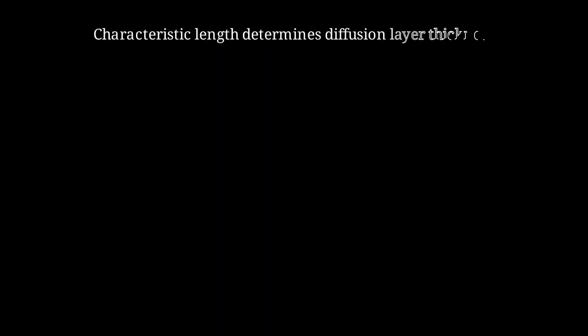The channel width, typically 100 to 1000 micrometers, determines the diffusion layer thickness and residence time. Diffusion layer thickness delta is approximately the square root of diffusion coefficient times time. Residence time equals channel length over average velocity. This must be sufficient for reaction completion.